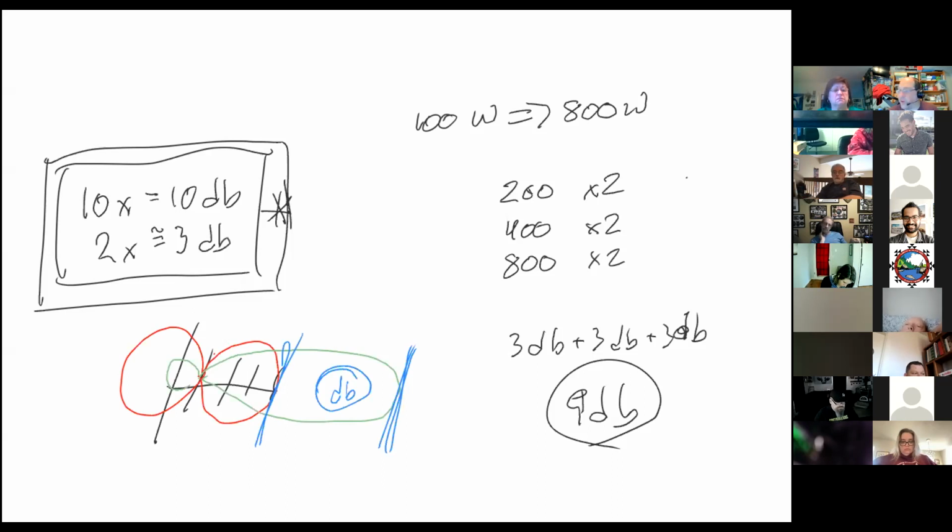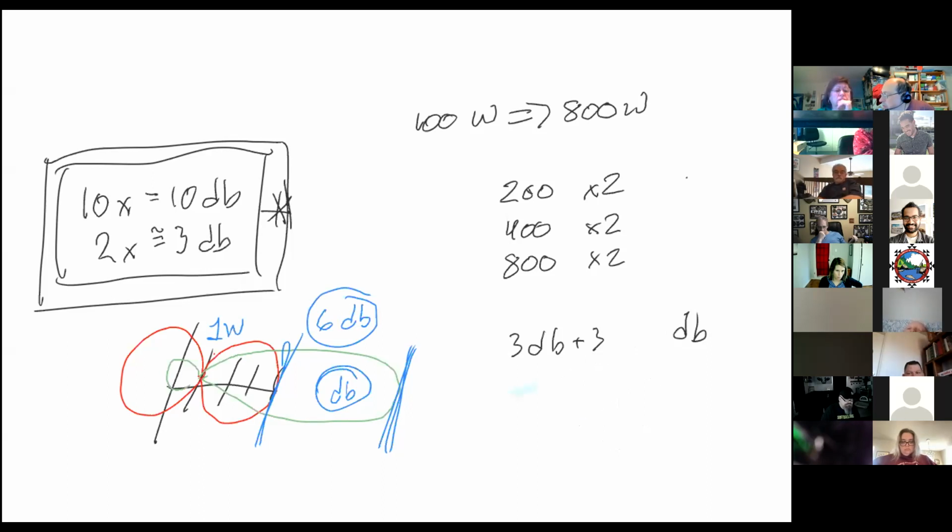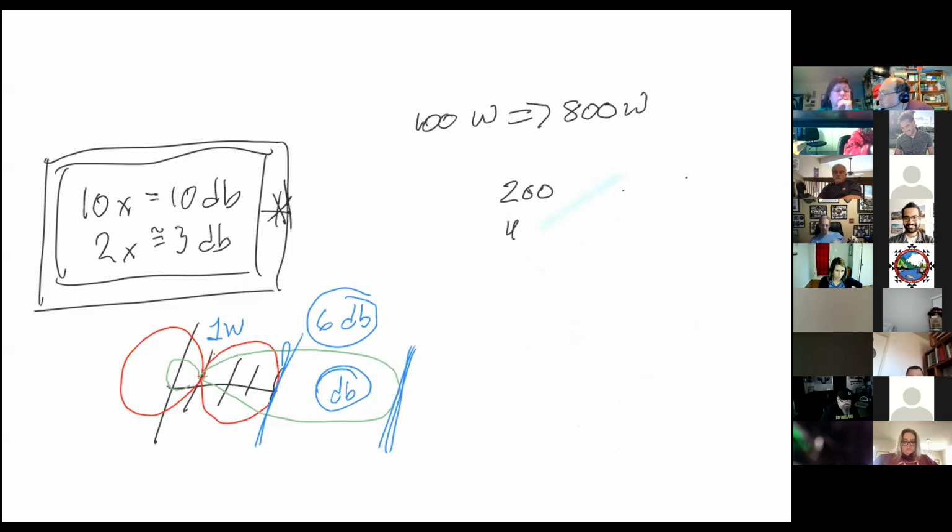So you can actually figure out, okay, if I use an antenna with, let's say, 7 dB of gain, and that means that I can conceivably have the same, let's say my transmitter is 1 watt. Actually, let's use 6, because 6 is easier to deal with. So I have 1 watt with a transmitter, with an antenna that has 6 dB of forward gain.